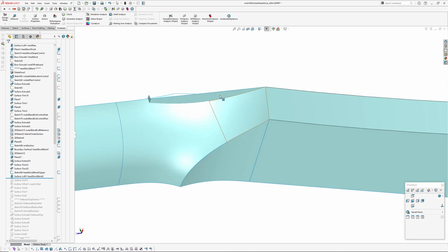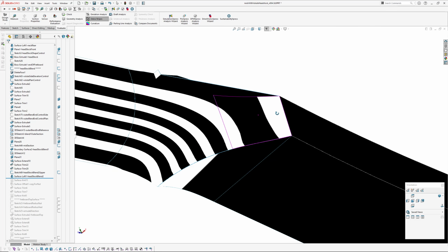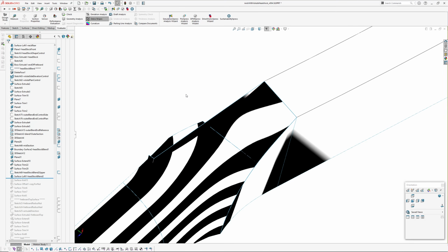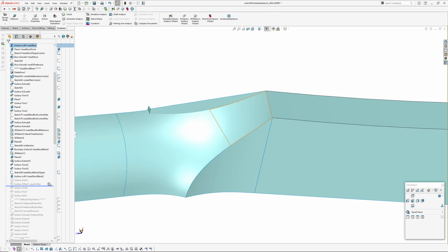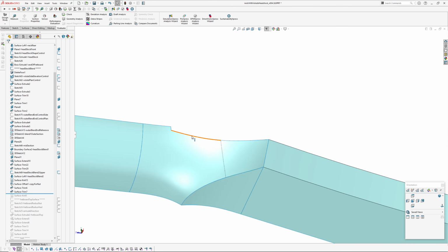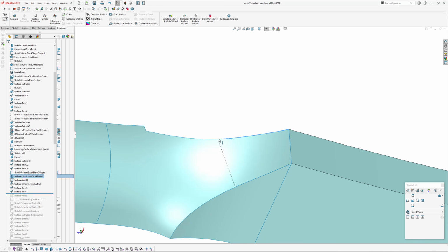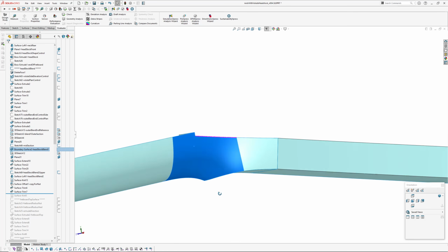And then that is created as a four-sided loft. I found I was getting better results with a loft than with a boundary surface. Okay, that's knitted together. Got a copy of this for making the nut further down. Then I've just got a few trimming operations here. As you can see, that's a resultant. So this is the resultant edge I was talking about. This one here is defined, but it is also reliant on where the surface sits in 3D space.